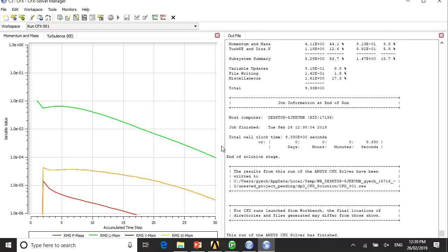The residual drops, nicely converging and so forth. You will see that in some of your problems, you don't get this. Sometimes it could be fluctuating and never reach 1e minus 4. All right? And you ask yourself, what's happening? Why am I not getting the convergence? So there are a few guidelines I can offer you.